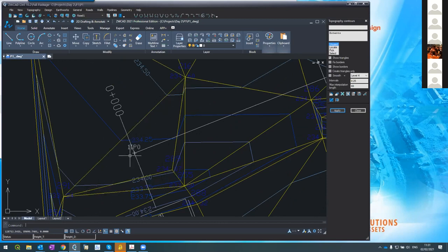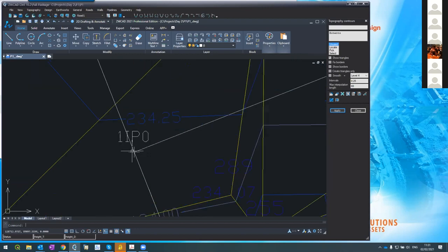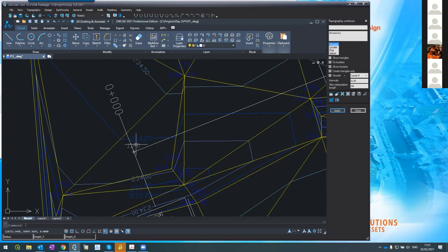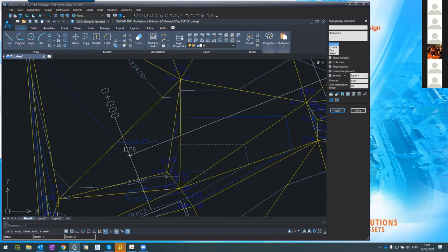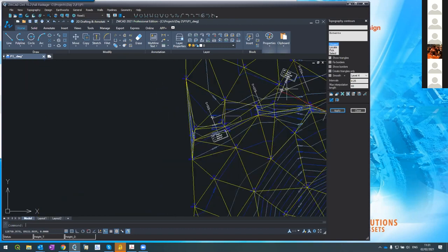Since this is a surface, the system extracted this point, interpolated this point on the surface, and this is the elevation that you got in the profile. Then the system continued, and after 5.6 meters, which is this, it encountered a change in the surface. This is a new surface. So the system did an interpolation between this point, this point and this point in 3D, and you got the change in the surface here. Then the same here, the same here, and so on and so forth.